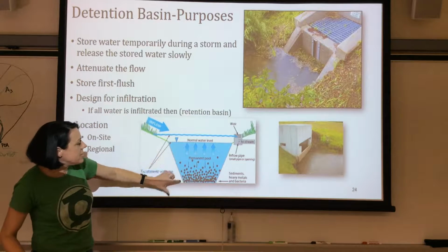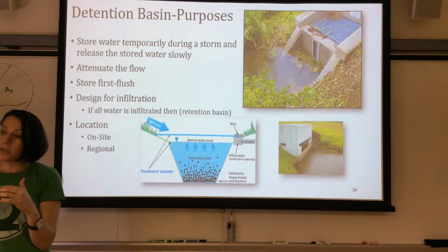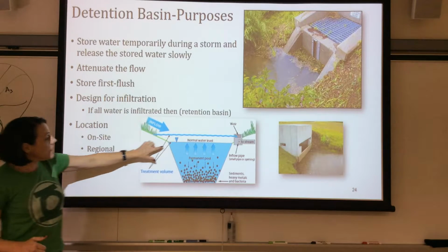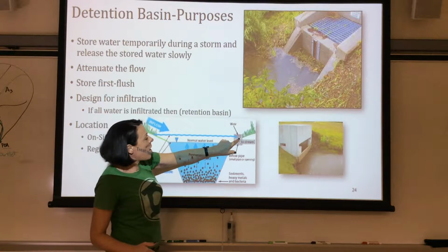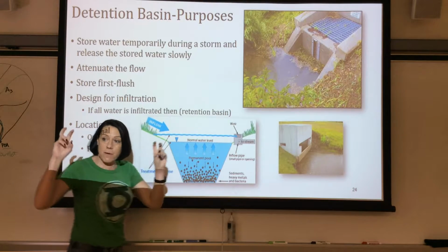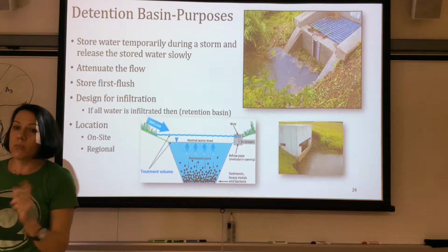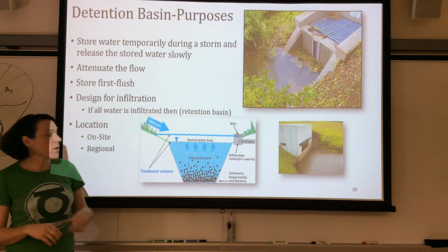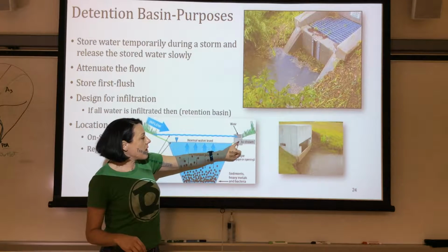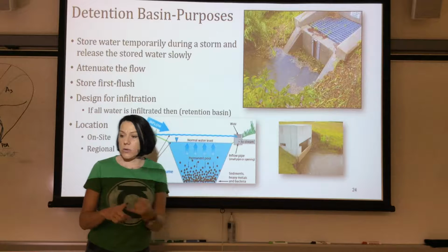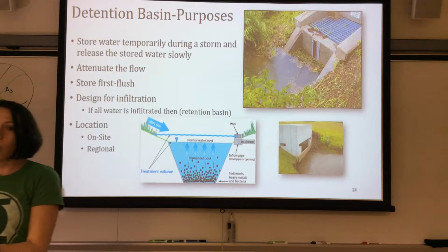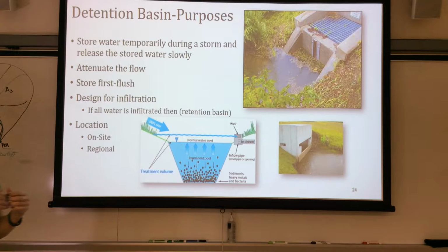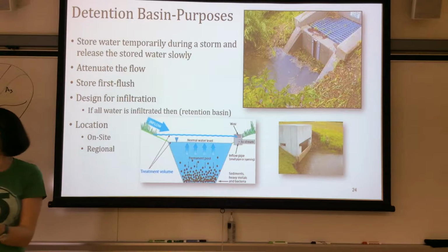So it has to be a certain depth to let all that pollution settle down to the bottom. Anything from the water elevation to where the water is being discharged over some type of water quality treatment volume weir, that will be how much treatment volume we have. We'll have a pipe that goes from our structure inside that box to either a stream, a wetland, or a pond downstream of it, or even a pipe system or a ditch like in a roadway.